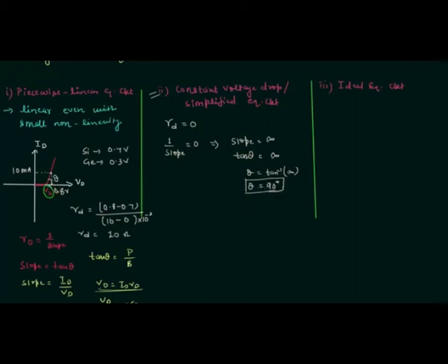So it is very easy to plot the curve Id Vd. We still have the barrier potential Vb, but the diode resistance is equal to 0. So we have plot like this. This is theta equal to 90 degree, and this shows the diode resistance Rd is equal to 0. This is Vb, and it is equal to 0.7 for silicon and 0.3 for germanium. So this is how the characteristics looks for constant voltage drop model.